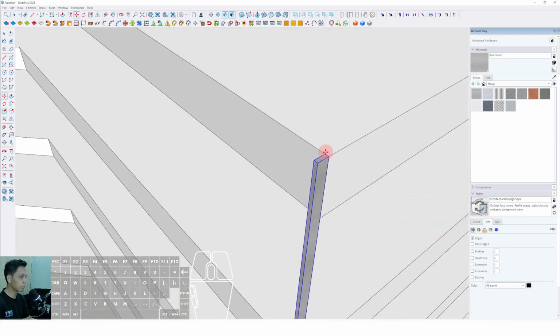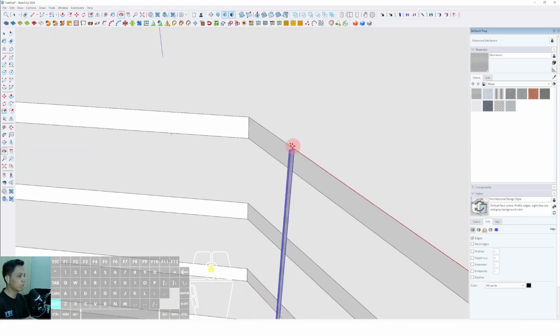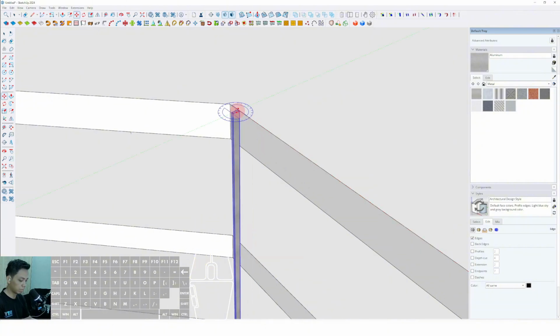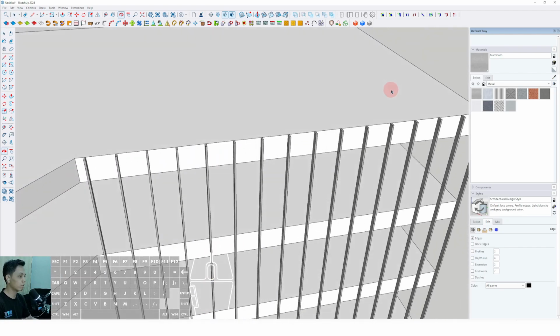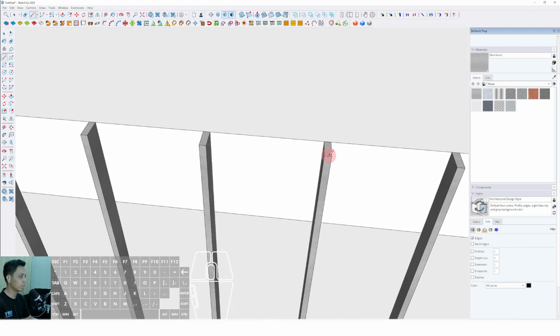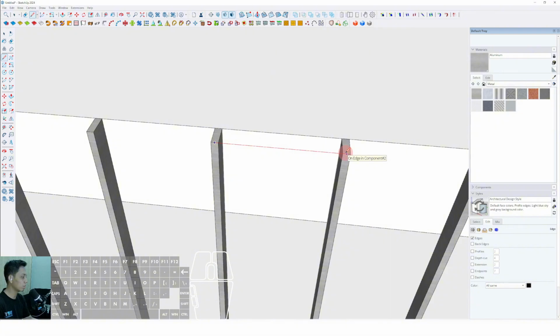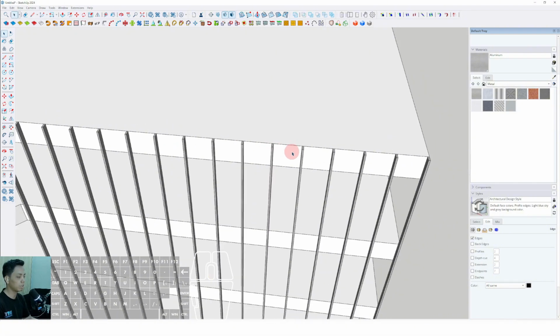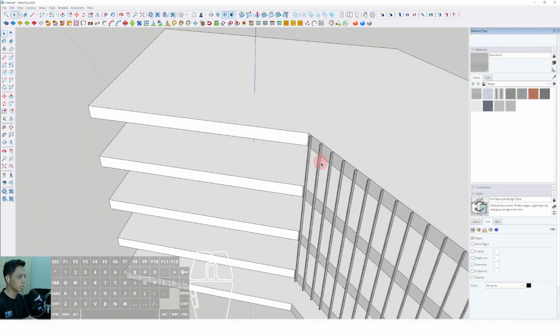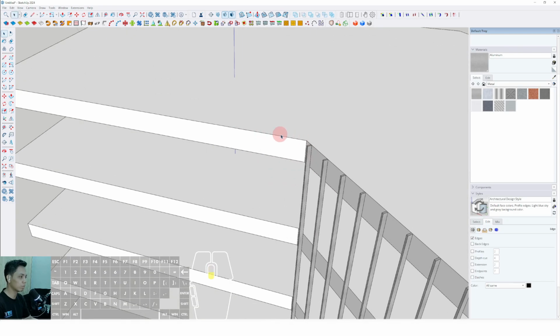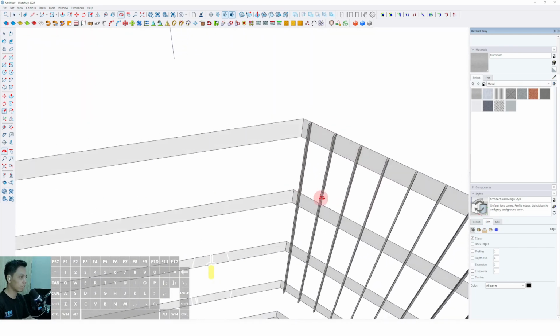Okay, we can select move, press Ctrl, then place to this position. Then we can type 15 slash enter. Okay, so we can get the distance of every single frame around 1.1 meter. I mean, it makes sense as a distance between the vertical frames for the facade of this whole building.